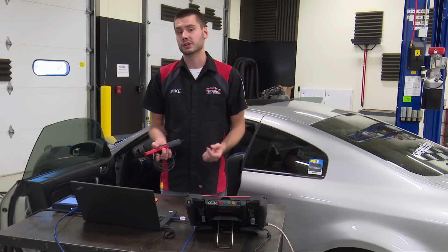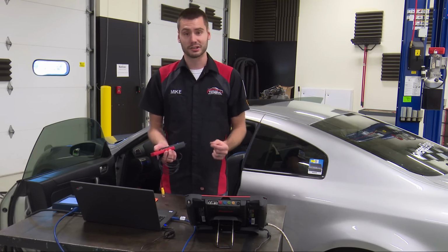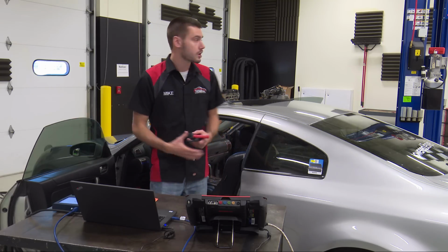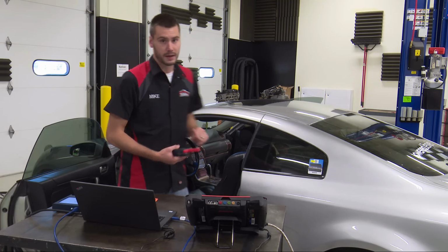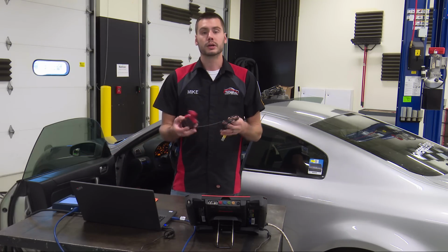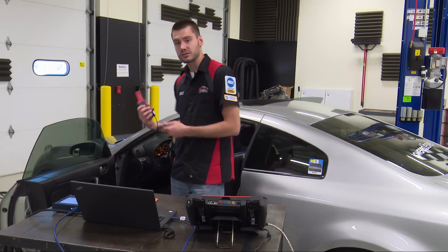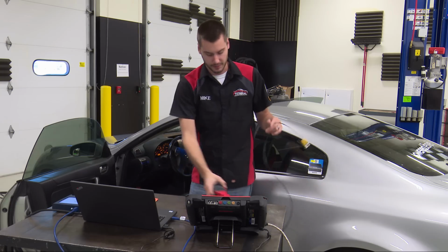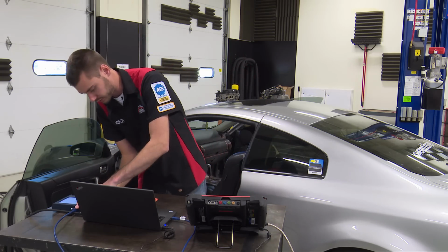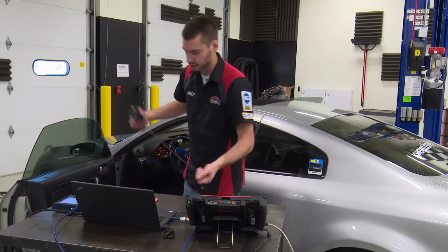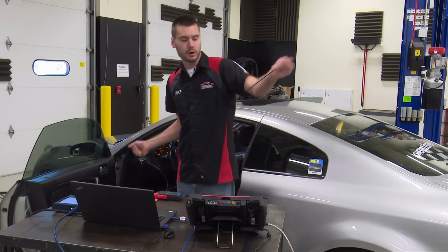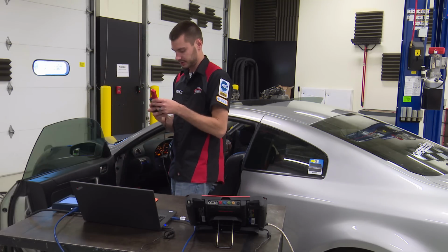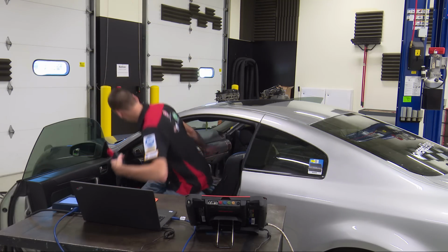Now what's nice about window circuits is usually you can get a known good pattern right away, right? We have a functional driver's side window. We have a questionable passenger side window. So we hook this clamp up, driver's side, passenger side, and we can compare the two. So let's get these all hooked up. Again, I'm on the 20 amp mode. We'll hook this one into channel A. We'll run channel A, our blue trace, for our driver's door. And then we'll run channel B, our red trace, for our passenger side door.